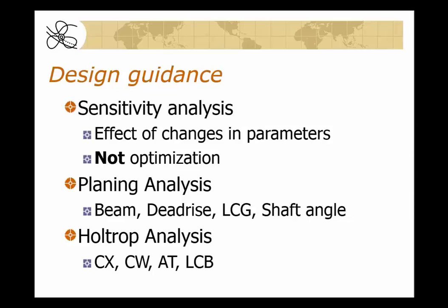Now, the third feature of the Orca3D analysis is a design guidance that I had mentioned earlier. This is really a sensitivity analysis. It provides a summary of the effect of changes in hull parameters. And I want to stress this is not optimization.